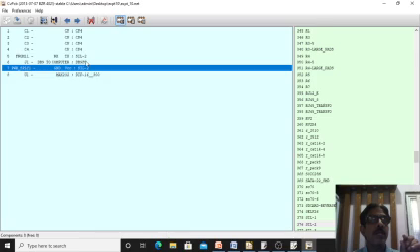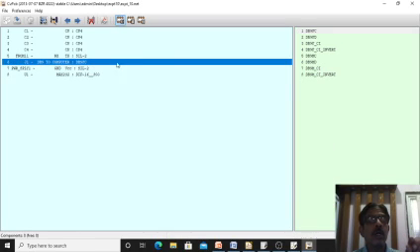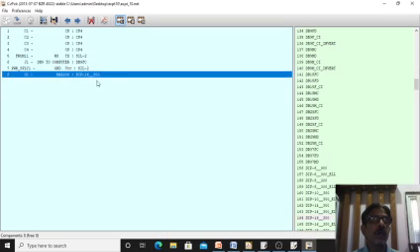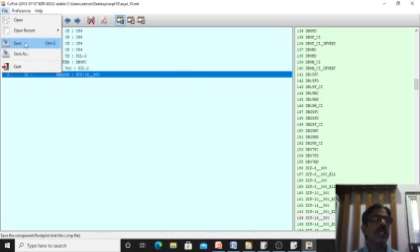And for DB9 connector I have chosen the connection as DB9FC, this I have taken. And for MAX232 IC I have associated DIP16_300. That is, it is a dual inline package 16-pin IC. That's why I have chosen this. In this way, associate all the components, then say save. Okay, then say quit. Okay, so you come out of this.